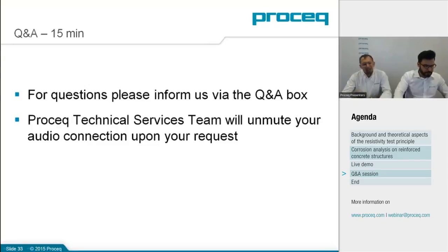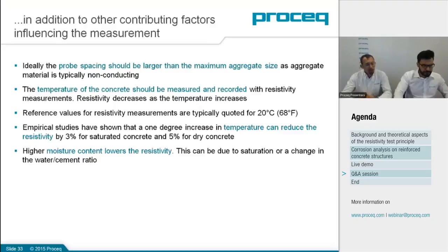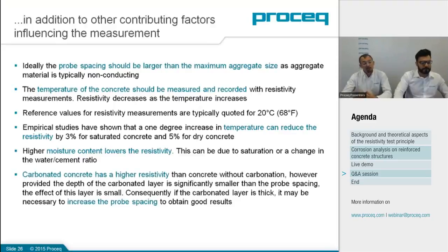The point is that there is no actual modeling of the variation of resistivity over a huge temperature interval. The key point is that we don't really need that, because it will always be a qualitative comparative test that we do on one specific day or one specific week over the structure. So all the different areas of the structure will be affected equally. They might be shifted up or down, but just keep track of the temperature. Yeah, exactly. So these are obviously an indication.